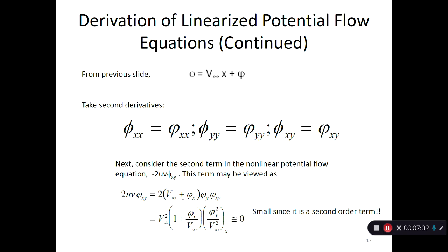non-dimensional form of this velocity. So I have taken one of the v infinity outside, so it became v infinity. I non-dimensionalized phi y by v infinity. Then I got a v infinity squared. Okay, so this term is small. So anything squared, remember this is like 0.1. When you square it, 0.01. The derivative we assume is small. So we're going to throw away this term. So we are using an order of magnitude approach and are making some assumptions and discarding terms in our attempt to make these governing equations linear.